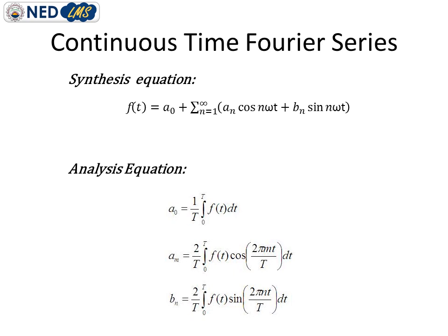So if you have any complicated waveform and you have to determine whether it has some DC offset or not, you have to use the expression A naught, the first expression highlighted by my pointer. This is the expression you can use to find the DC offset in any complicated waveform. And if you want to determine the cosine wave with a particular frequency, m is an integer, and it will be multiplied by 1 over T, which means frequency.